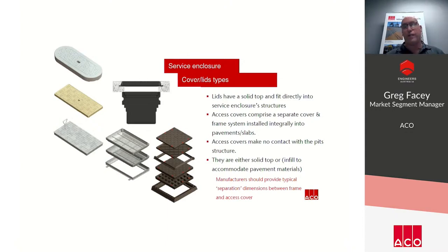So plastic single wall pits, again, if you remember, are suitable for landscape and pedestrian applications. So even though the lid might be Class D, those loads can be transferred through the plastic pit. Even though a Class D cover is fully supported by the surrounding slab, do not use a single wall plastic pit below that. If you're using a Class D cover, you need to look to a rigid pit, either in a polymer concrete style material, or a twin walled rigid plastic pit material. That's one thing that we do see come up often. So just consider it's still the right pit for the application.